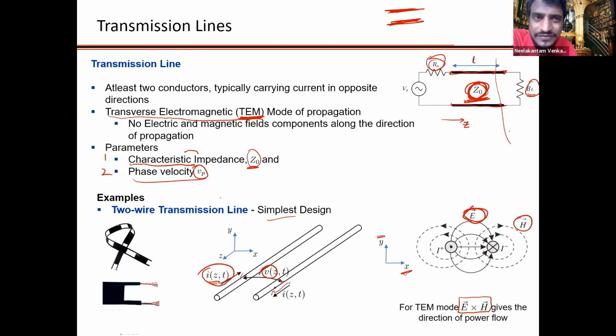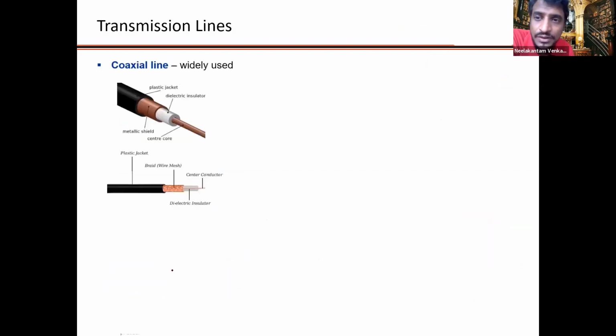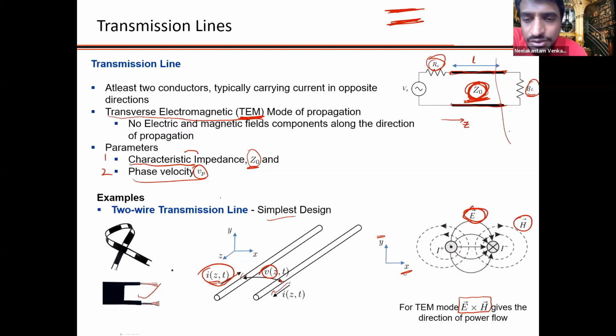So this kind of two-wire transmission line used to be very popular in the past for TV cables, for TV antennas, from aerial to the TV box. But these days, nobody uses that. But some military applications still use these kind of two-wire cables. The other kind is a coaxial cable, which you are more familiar with. Here you see that this is plus I and minus I. That means the current directions are plus and minus. So you need these two conductors to realize this transmission line.